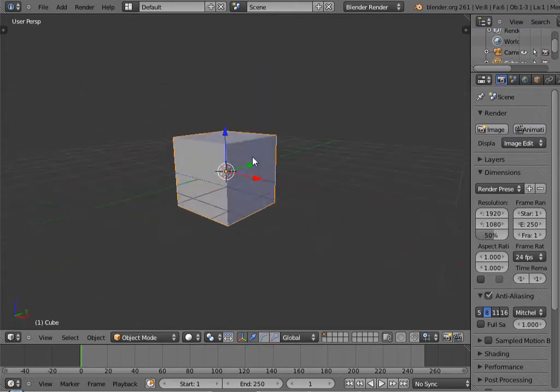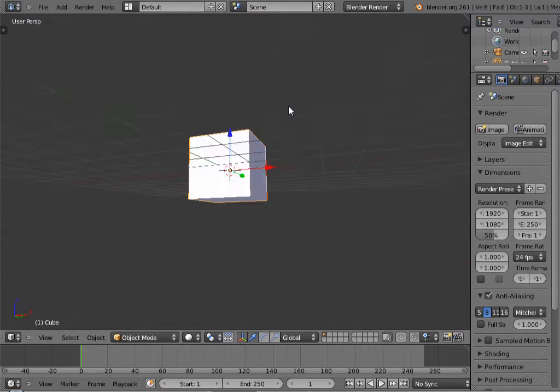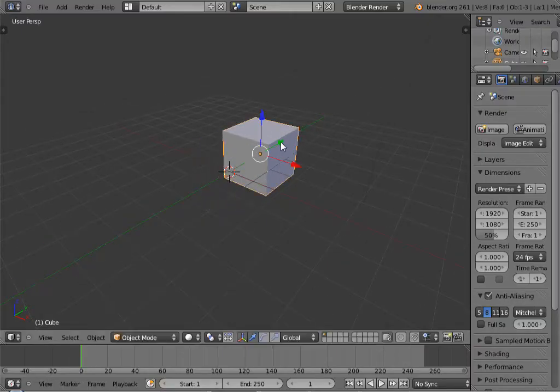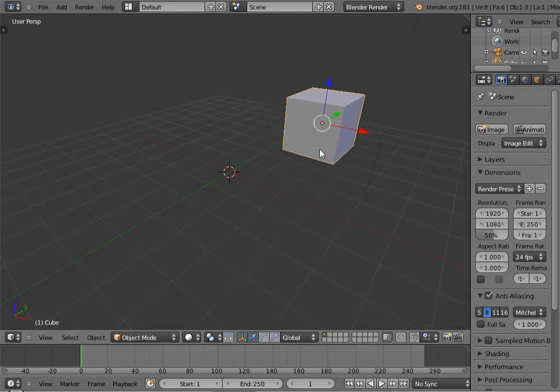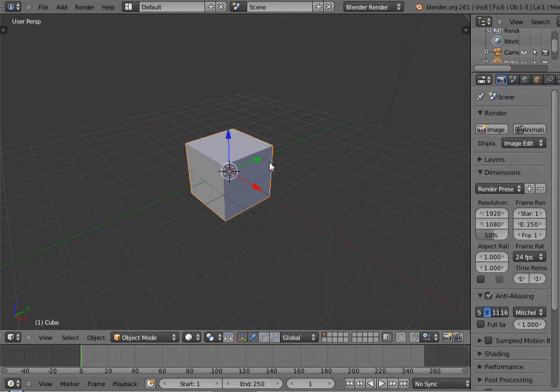Anyway, the first thing I'm going to make is the tall blue building with the black sides, since that's a fairly simple object to start with. Now you can move the object around on these axes by grabbing these little gizmos and moving them. Now I don't want to do that, so I'm going to Control Z a few times to get back to where we were. Let's see, first thing to do is to make this taller, so I'm going to press S.